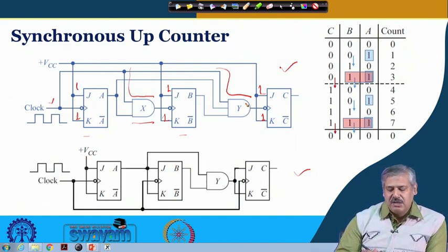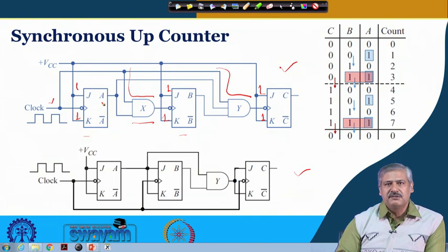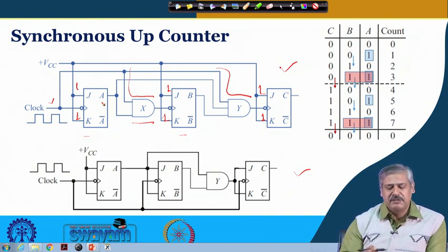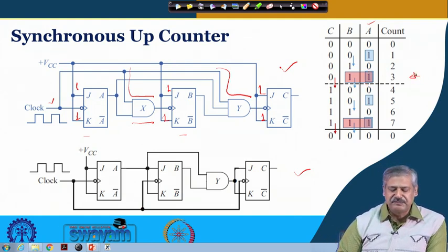Of course, there is no AND logic here. So at every clock trigger, flip flop A toggles the way we expect, the least significant bit in a CBA configuration. A is toggling every time, 0 1 0 1 0 1. More about these boxes I shall discuss later, in this diagram, in this table.